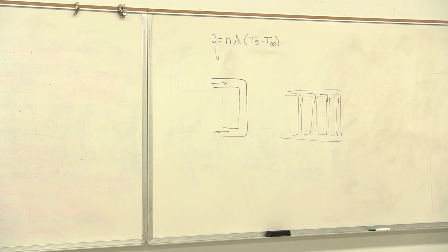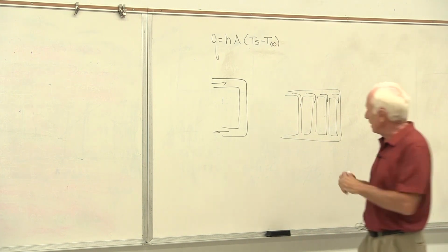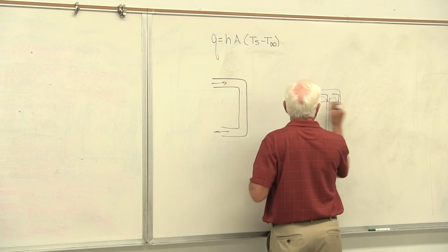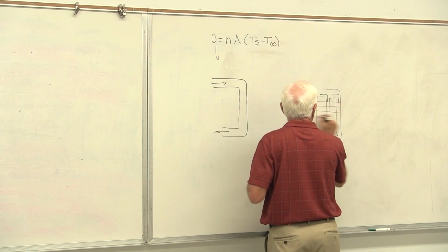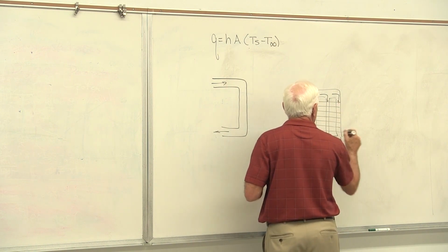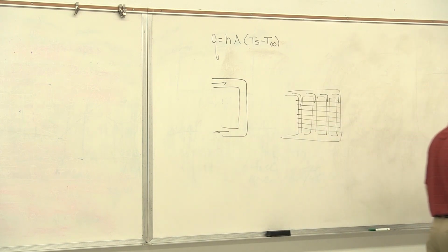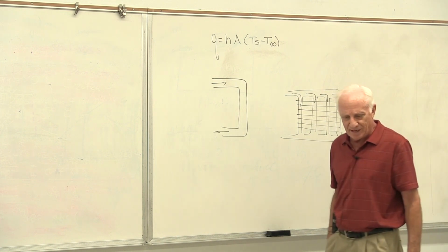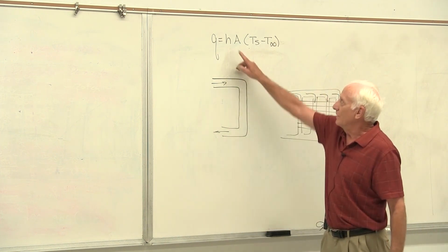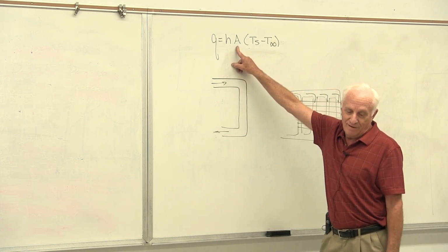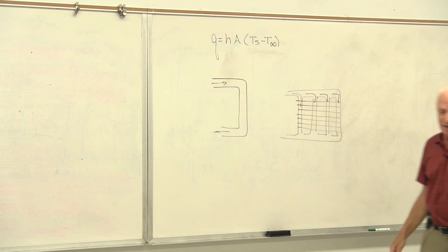Another guy says, you know what? I could do more than that for you. I'm going to put flat pieces of metal, little strips of metal, between these tubes. And I'm going to call these fins. And boy, will that increase the area. Oh, you got that right. Try and count the fins in your automotive radiator sometime. It's like counting tree rings. Get a big magnifying glass. Oh my gosh, there's a lot of fins in there. That's a humongous area. So what do engineers do? Oh, they crank this guy here up. Everything we do to take heat out of something is that way.